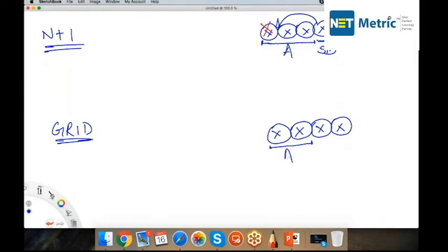If I have four power supply units, any three power supplies are made active. The other one is kept in standby. If any of these active power supplies goes down, the standby becomes active. This is what is N plus 1.